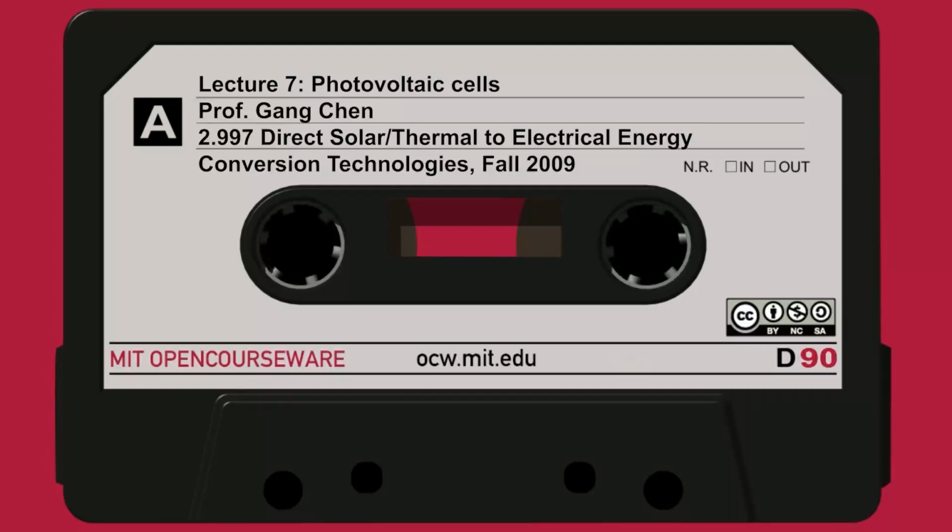And the longer wavelengths, lower energy, can transmit through. So they get absorbed in the second layer, and also the third. That's the idea. And of course you can see with this stacking, each one generates a current, right? If you look at this, the key is that your current has to be continuous because you put an electrode on top and an electrode on bottom. So each cell has to generate the same amount of current.